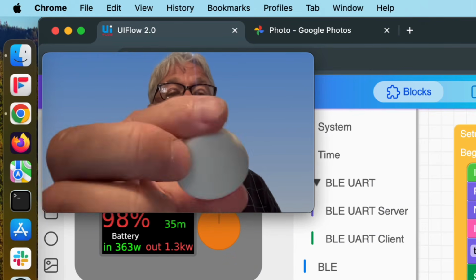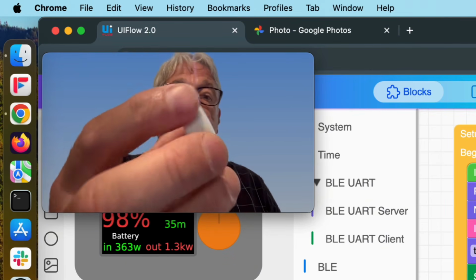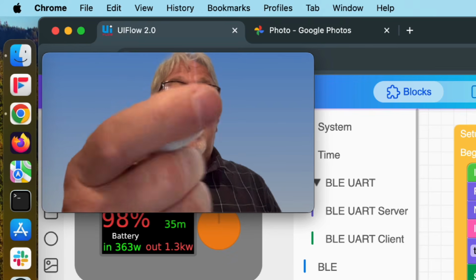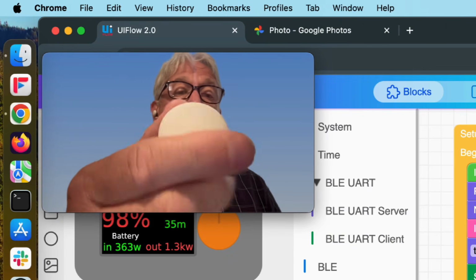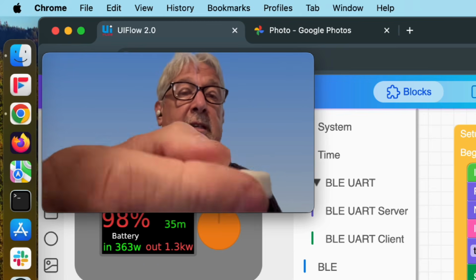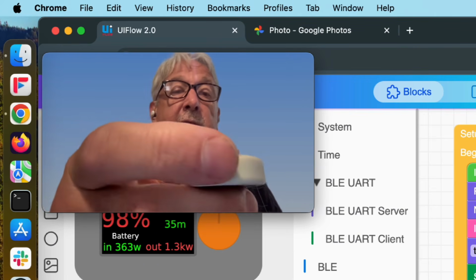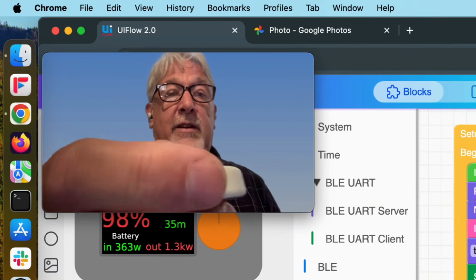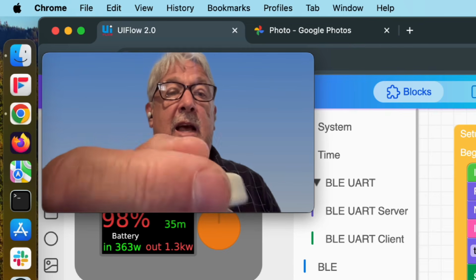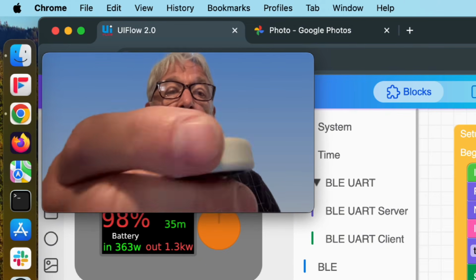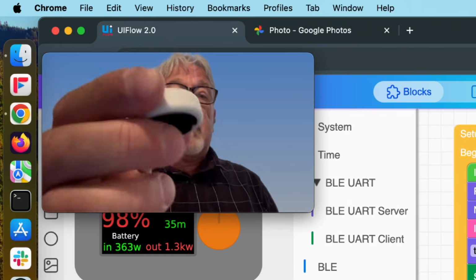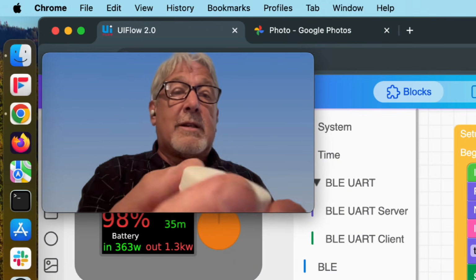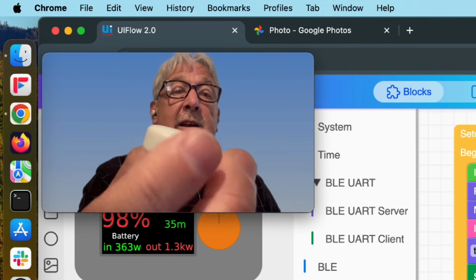And basically, once it's seen numbers that are in the range it already has, highest and lowest, it flashes green. So you basically rotate this until you get no red flashes. You spin it around this way, you rotate it, and then you put it down on a flat surface and press again, and that then locks in those as the 0 and 90 degrees for the different sort of XYZ axes, and it also gets any offset so that everything starts at 0 in that position. So then I can measure its movement very sensitively. So if you were to rotate this, I use a HID and I rotate it clockwise.